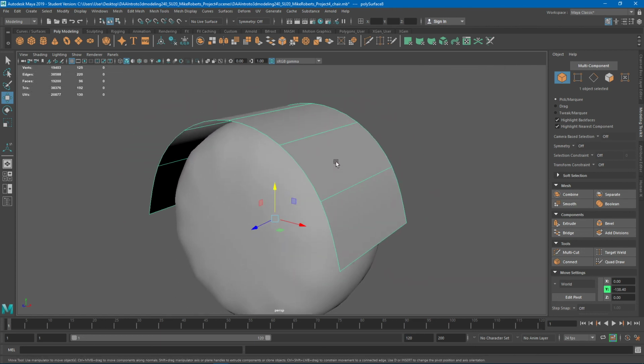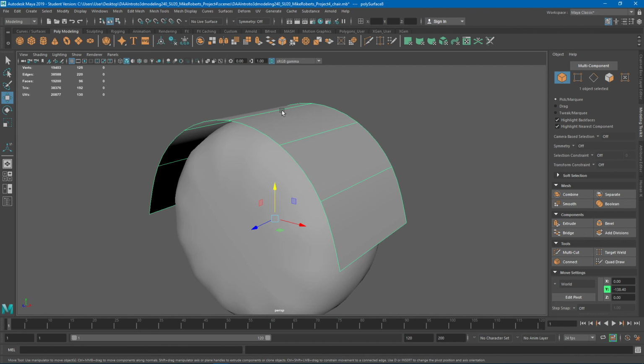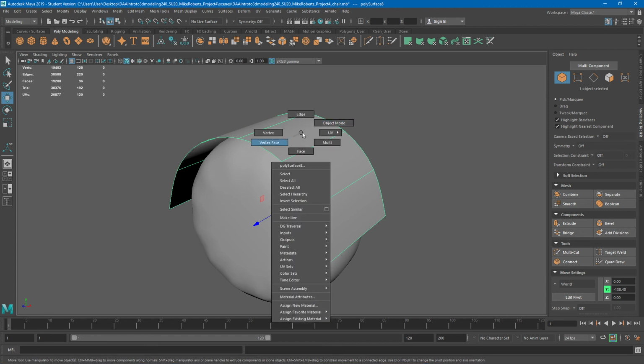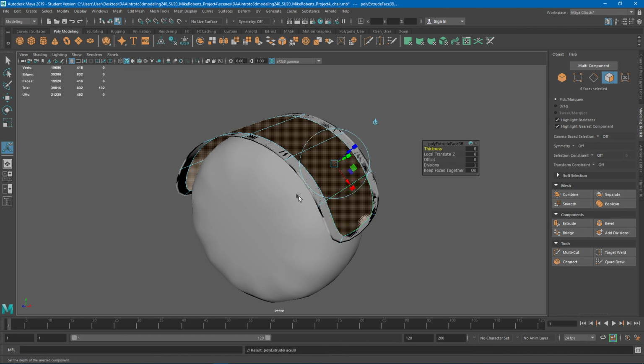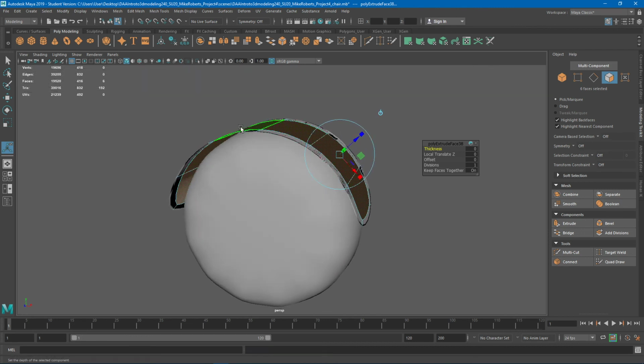So in this case, I make sure I'm in object mode, right? Hold down right mouse button, object mode. Click on this sheath here that we've created. And we want to thicken this, don't we? And if we stay in object mode, right? Hold down right mouse button, object mode, green wireframe, and we extrude in object mode, it thickens, right? Because it notices that all the polygons are selected, so it says there's a 99% chance you want to thicken, which is true. If you only have some faces selected, it's going to do a regular extrusion, which 99% of the time is what you want there also.